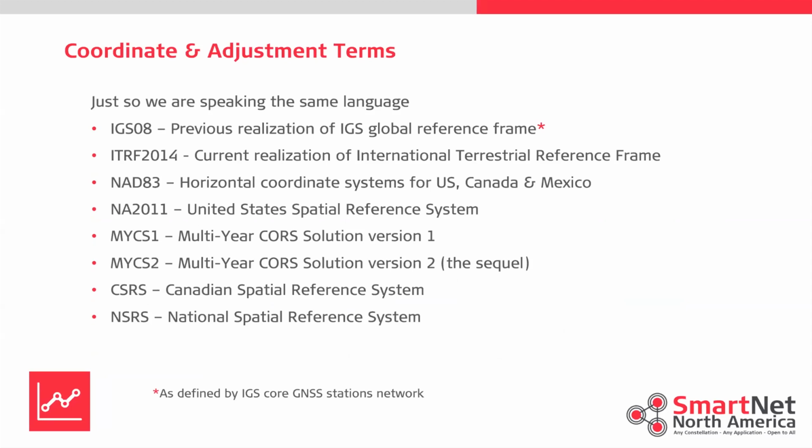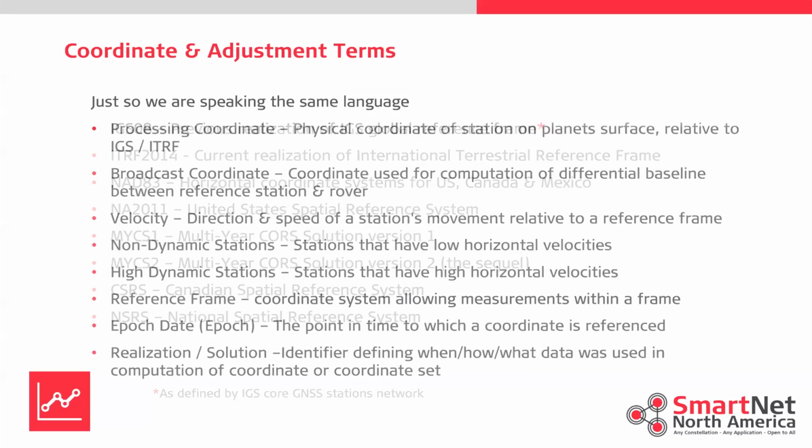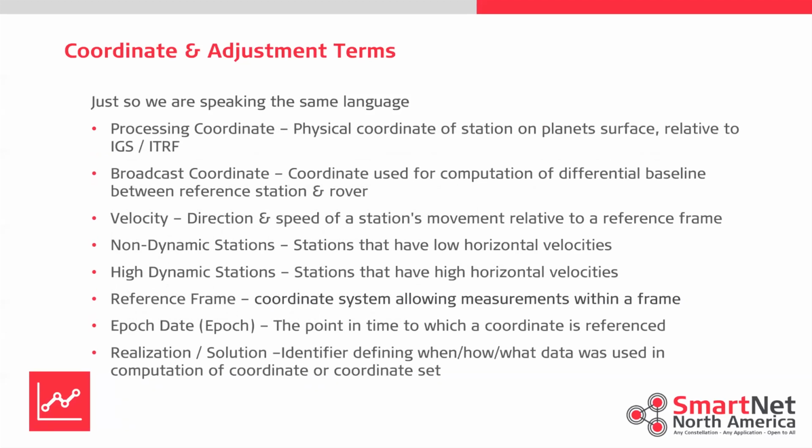So we're getting a couple questions. What is a reference station? What is a reference frame? Those questions, if we're going down that road, a reference frame is simply, like I said, the coordinate system allowing measurements between points. So if we talk about the coordinate system that I'm operating in, that would be the reference frame. And there are different reference frames in different regional areas, different countries, for different needs. And we have three primary reference frames that we talk about in this application, which is on this next slide.